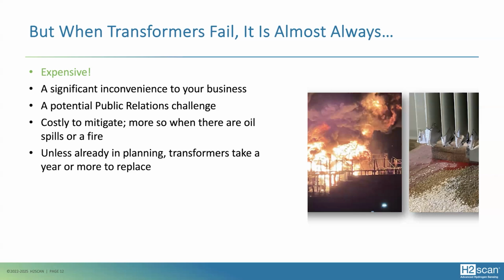Those days of us just pouring sand over a large oil spill and moving along are gone. And there's a lot of cleanup costs. But most importantly, and I think we're all very familiar with this, unless you were already planning to replace a transformer and the delivery of the new one is imminent, they can take a year to replace. If you go off-brand, perhaps you can get something a little bit sooner if you import it, but your risk associated with an off-brand transformer might not be the same.